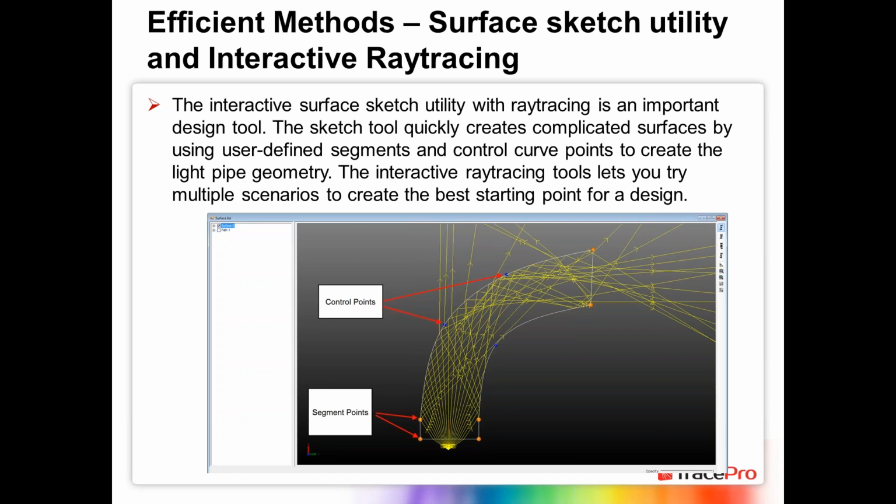And you then specify an LED that has a divergence, and I've put it out to about 55 degrees here. And I want to see how much light's going to come out. Now, you can see that at the bend, you have light leaking out. You always are going to have light leak out because you're going to go beyond the critical angle at some point. But you're trying to maximize how much light you keep in.